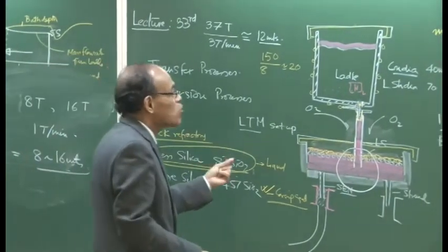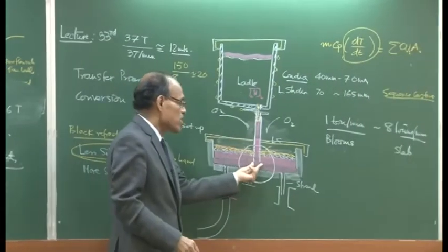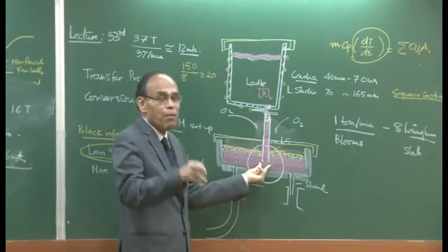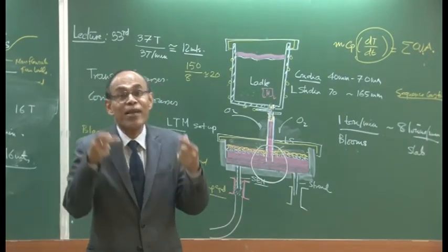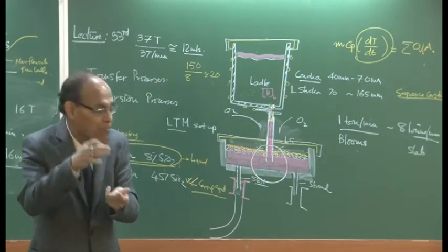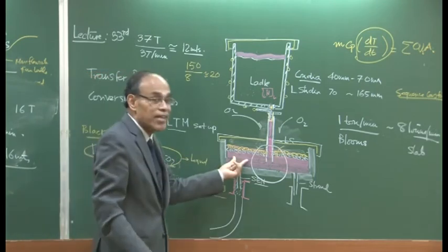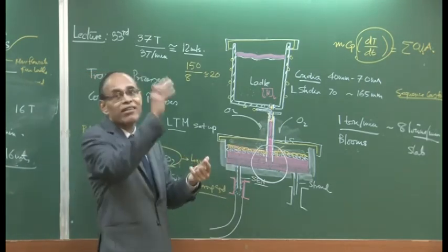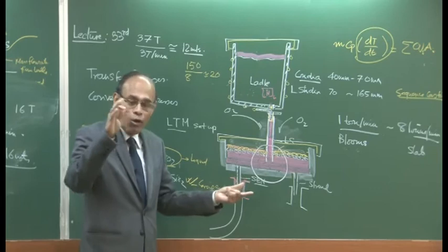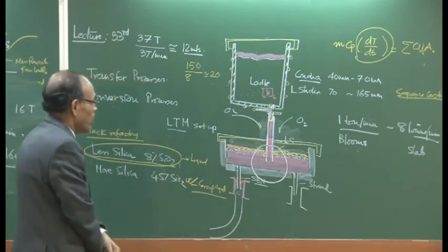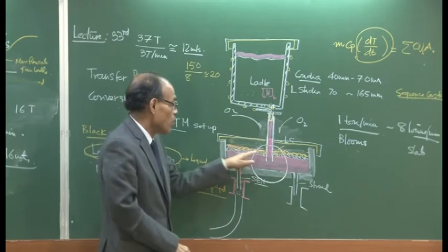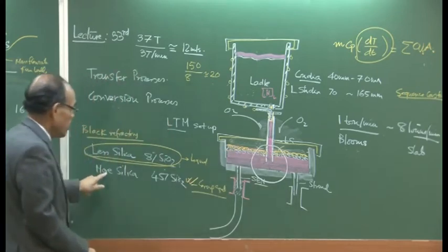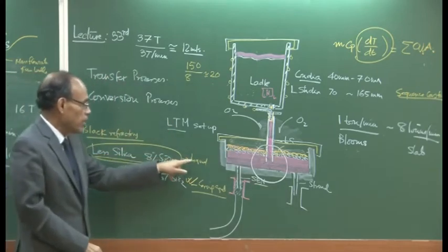It is sufficient for us to note that the fluid will spend some amount of time in the tundish. So the issue is, can we exploit that residence time to further improve the cleanliness of steel, or further help steel float inclusions which can be absorbed by the slag, which is in the liquid state.